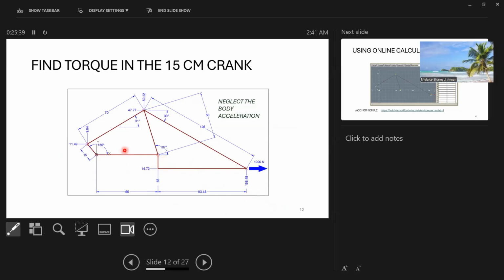All right, so if you have this kind of problem, you have to decide when you want to use the Grashof equation criterion. You will focus that on the 4-bar mechanism part. This one is the slider crank part, so for that, do not use the Grashof equation. Okay.